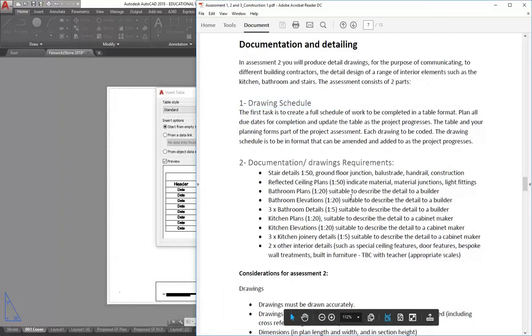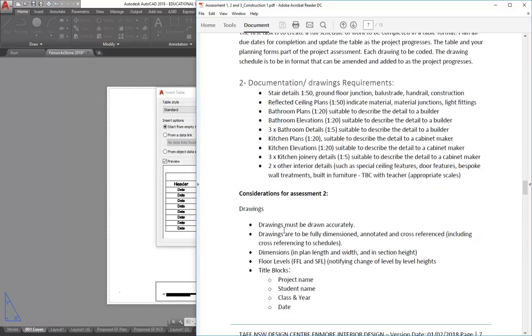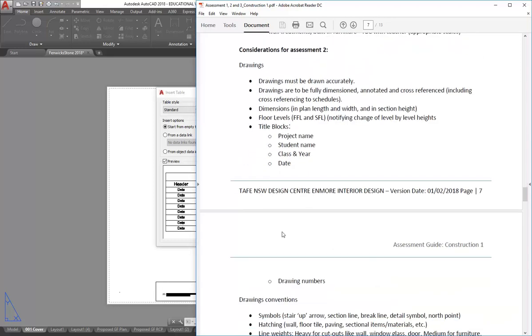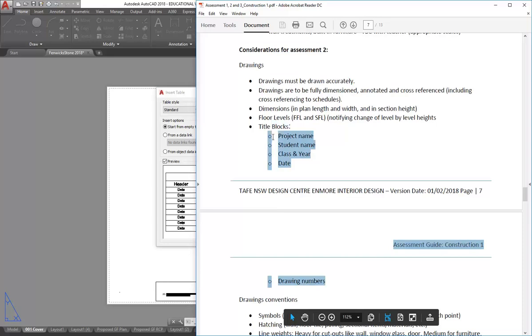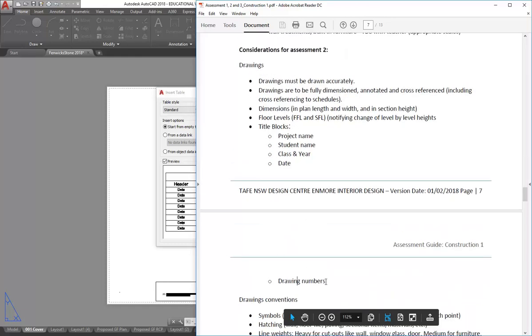So looking at the drawing list here, you might get some idea, and what I thought actually would be good here is if we look at the title block options. That'll often give you a good idea of the sorts of things that you might want to include in a drawing list. There's no real rule for this, but it really comes down to common sense. So starting here with one at the bottom, the drawing number, usually will be the first thing. Then you'll have the drawing name, which unfortunately isn't in this list, but that should always be in a title block as well.